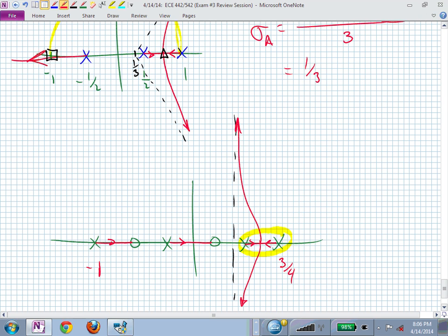No, because those infinite zeros are going to go outside the unit circle, aren't they, at some point? And it's going to depend on where that centroid is and where they bend around. K equals 0, is that stable? It rings, but it's stable, isn't it?